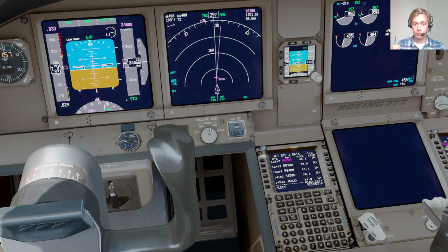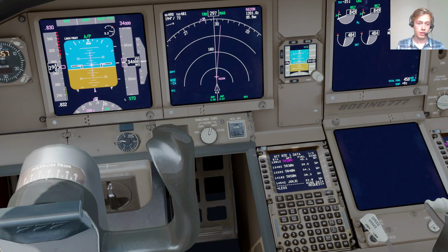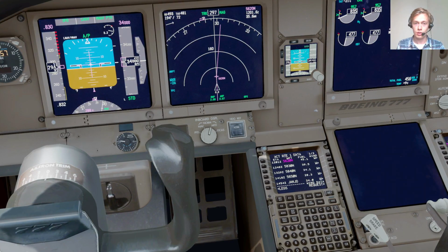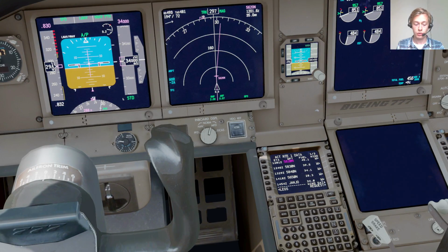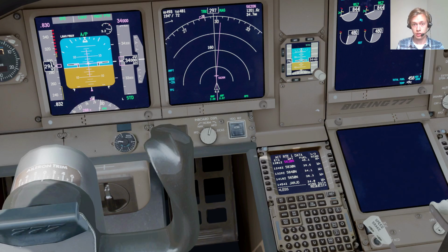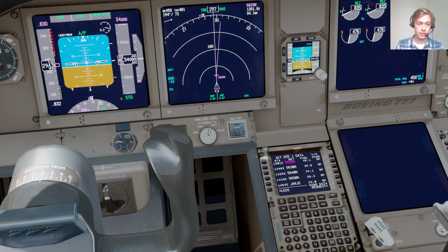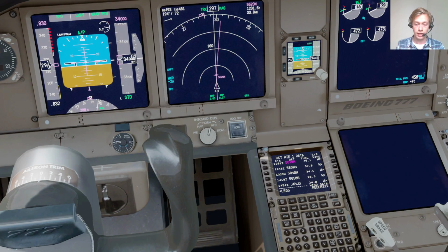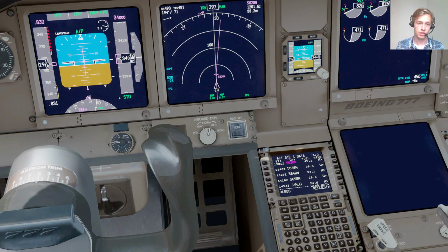So it requires a little bit of practice, and as you do this, you can also just try and do this offline, practice with yourself, and act as if you're talking to ATC doing position reports. It's pretty simple. It's a new type of phraseology that you have to learn. Alright, and you might have a little bit of hiccups, but always make sure you have that pen and paper next to you so you can write down the information of the controller.